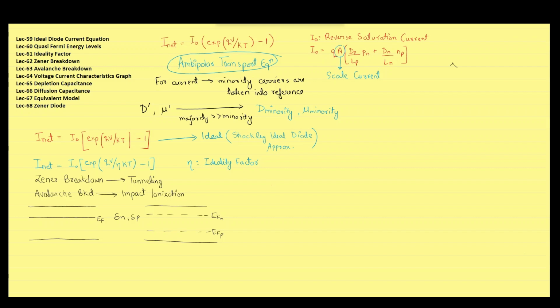After studying so many concepts, we finally constructed the graph for the voltage current characteristics of a diode. In the graph, we introduced another parameter which is cut-in voltage, defined as the reference voltage above which the current increases very sharply. Another parameter which we defined from the graph is GD, called incremental conductance, which is the slope of the graph, approximately equal to the current passing through the junction divided by ideality factor times thermal voltage.